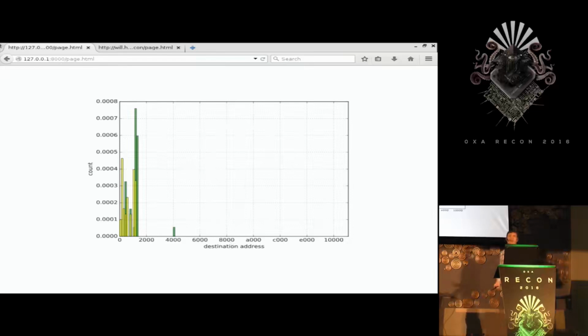So we have a pretty good guess at a relative jump, an absolute jump, and now possibly what we think might be a call. Because basically, silicon costs money. Unlike a malware VM where they're trying to deter you from analyzing it, the silicon is all about how can I build it in the simplest and cheapest way that it'll work. And an absolute jump is really similar to an absolute call. The only difference is that the absolute call has to push the return address onto the stack. So it makes sense just to have a single bit that says, hey, you're going to have to push the return address when you execute this.